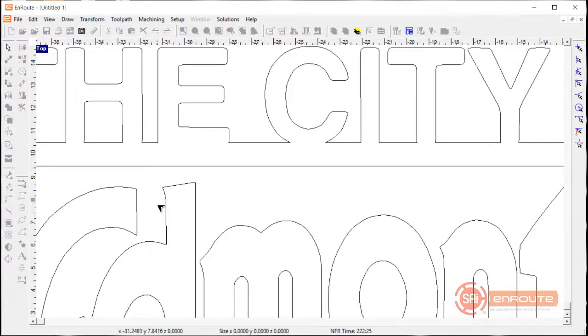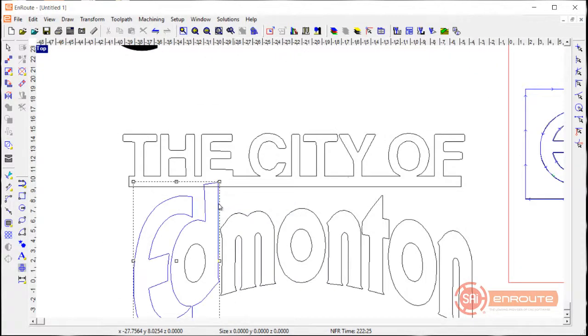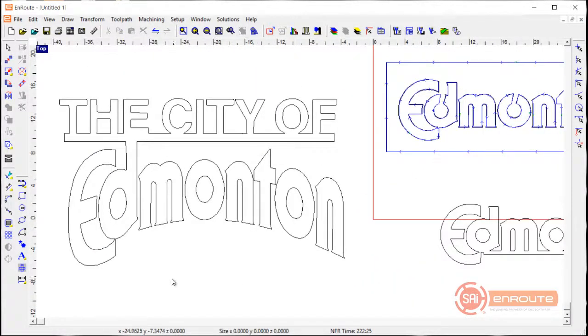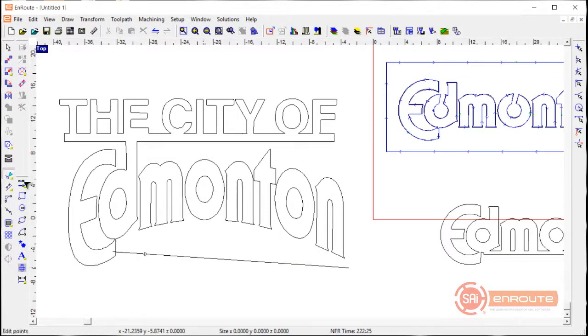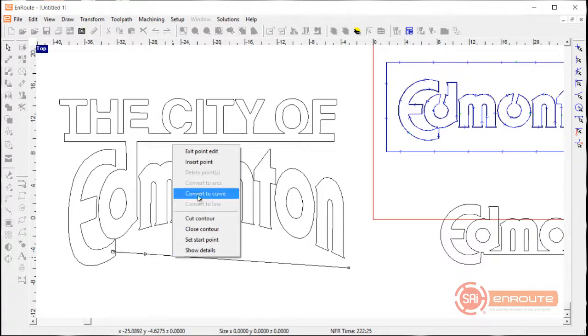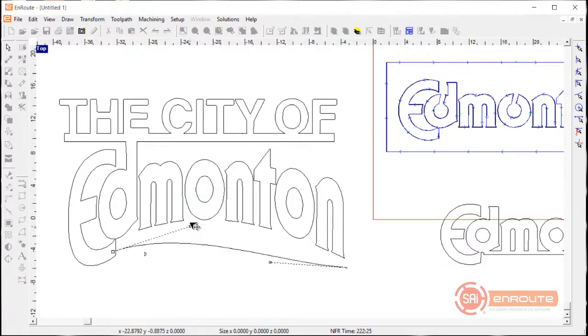All right, so we're going to go to the point edit mode here and start moving these up a little bit. So that's going to become the connection then between this contour and these contours. So I'll weld that together. Now we need a little something to go along here. So I'm just going to create a line here. Go here and make this a curve. That'll give me some handles that I can use to just make this line go all the way up.